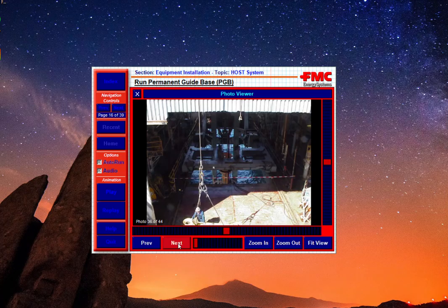The huge trolley, and the BOP is lifted by drill pipe or marine riser from the top drive and onto the trolley like this, that you put under the drill floor. You relieve the weight by setting the BOP or whatever it is on top of this trolley. You take off the running tool and you can take it on these rails out to the side.